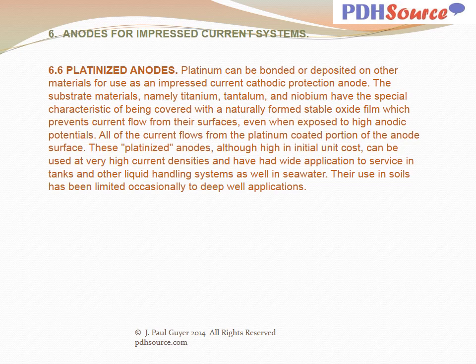These platinized anodes, although high in initial unit cost, can be used at very high current densities and have had wide application to service in tanks and other liquid handling systems as well as in seawater. Their use in soils has been limited occasionally to deep well applications.